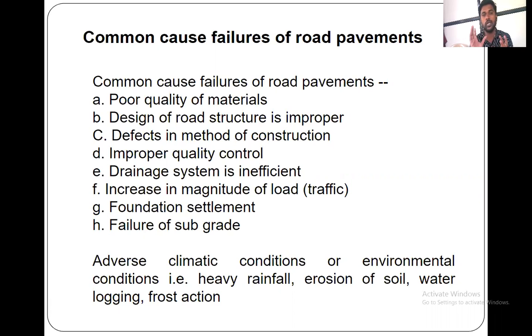Whatever the grade of concrete that you have used for the construction of the road, you have to maintain at least that grade or more to fill the potholes and the cracks. So good quality materials should be used there. Also, while filling the potholes of a flexible pavement, whatever materials we use should have the proper load carrying capacity that we used already in the flexible pavement, or more than that. Only then can we use that material in the maintenance work.